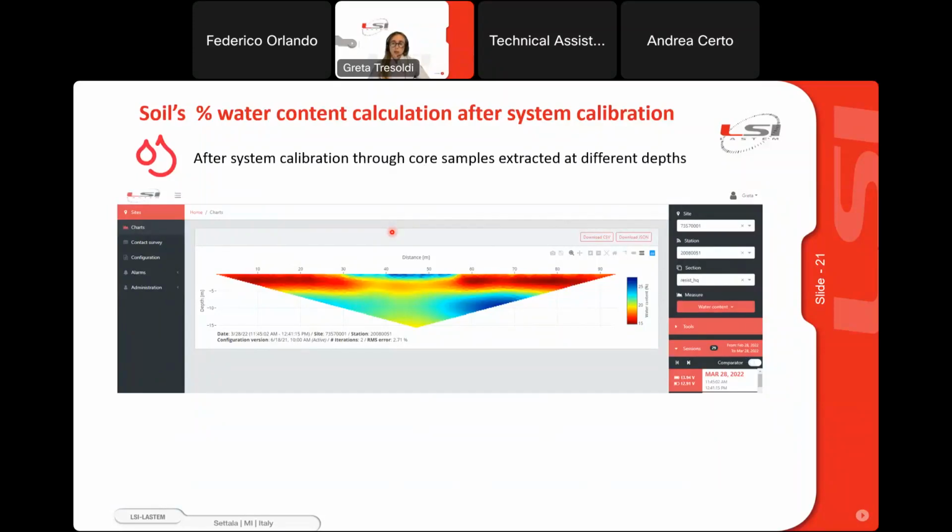The system can be also calibrated through core samples. So you need to do a core at site near the profile, extract different core samples at different depths, take the samples to the lab, measure directly the water content, and you can insert in the platform this curve that relates the 2 variables. And then you will obtain an estimation of water content, and you can visualize this section.